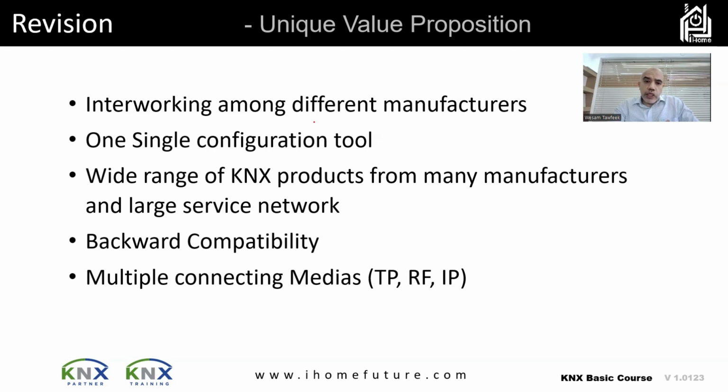Also, it's one single configuration tool, the ETS. So you have to learn only one tool, the ETS, or one protocol, the KNX, which allows you to implement a lot of devices in your project. It has different media, so I can connect KNX devices using the TP, the twisted pair cable, or I can also connect them using IP protocol, in this case like via Wi-Fi, fiber optics, anything like that. And also there is KNX RF, a radio frequency protocol, which will also let me connect my devices via wireless connection. And all of that was covered in the KNX Basic Certified course theory part.